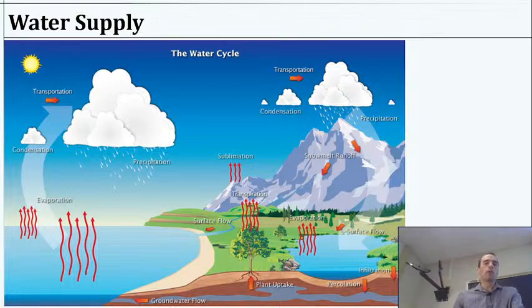So then we could use rainwater, so long as the route that we collect it and then make use of it and store it is relatively sanitary. If you're collecting it off of a rooftop and you happen to have birds nesting on your rooftop or landing on your rooftop, well, there's some possibility of getting some pathogens there, right, from the bird droppings. Now, maybe a roof keeps itself decently clean with all the sunshine and heat, but there's still some probability there that there's enough organic matter and shields the bacteria, lets them survive till they make their way into your water, right?